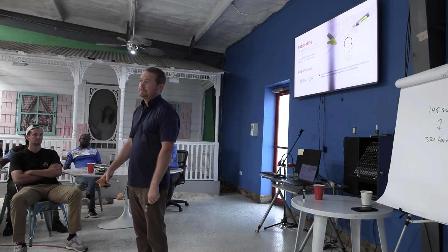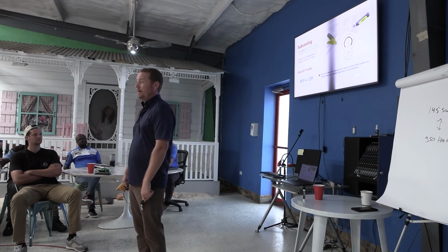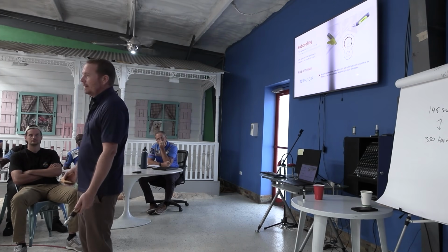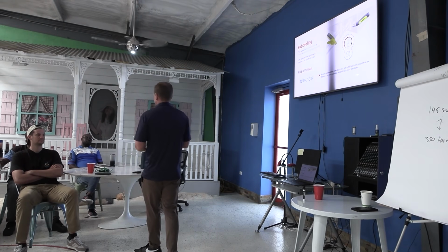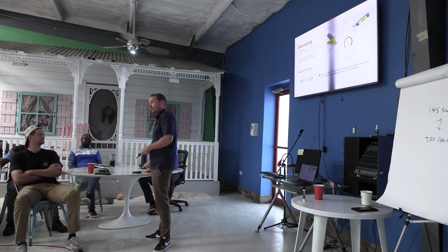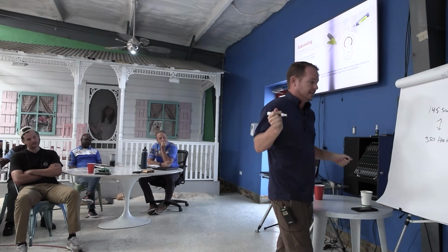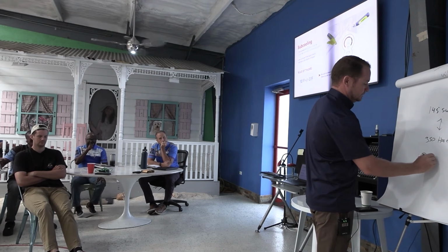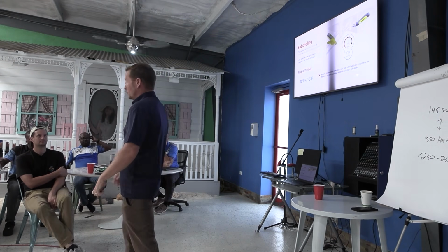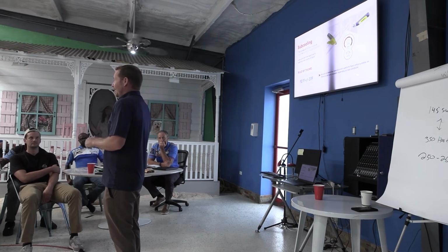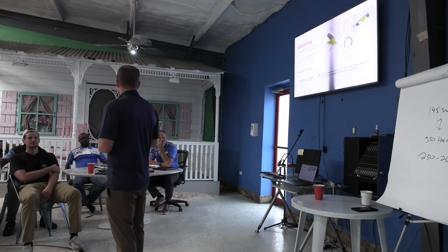What's our subcool? Zero. Well, if you follow what I'm telling you, zero superheat tells you have an overfed evaporator coil. None of that applies if the compressor's not running, right? None of this makes any sense if you don't have the primary heart doing what it's supposed to do. And that's where a lot of guys get really confused, because let's go back to compression ratio. What is the compression ratio of a system that's completely off? It's 1, right? It's 1 to 1. They're the same number. Wow, that's a really efficient compressor. And the answer is yes, it is. It is a very efficient compressor because it's not doing anything, right? And you're not putting any power in, right?